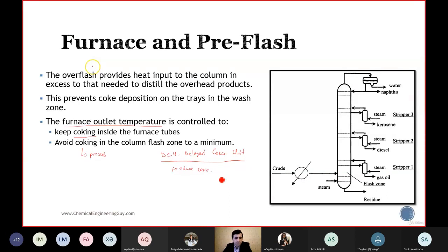So let's say if we have coking here, solid hydrocarbon formation here. It is really like a stone, and this reduces heat efficiency. You can also have a problem if this becomes bigger and bigger, then there is no way for your fluid to pass through it.